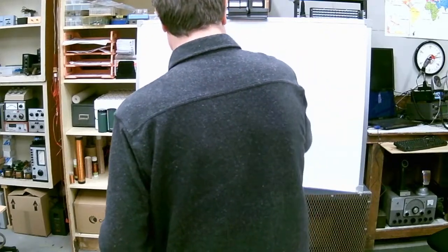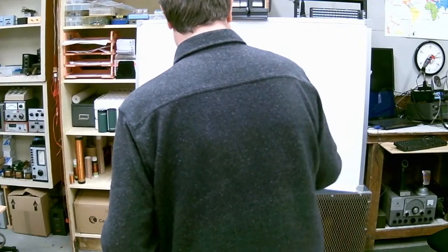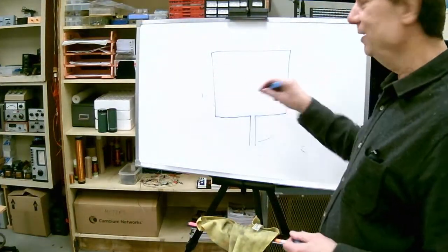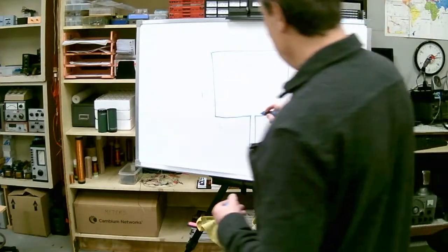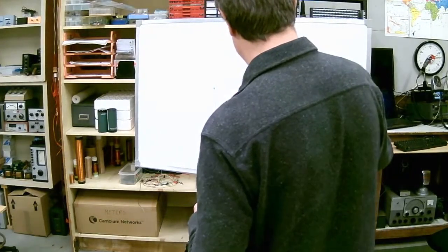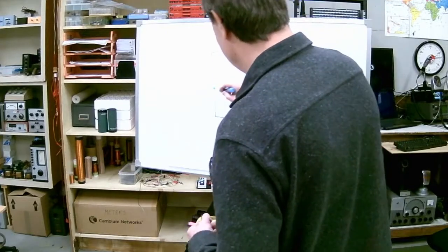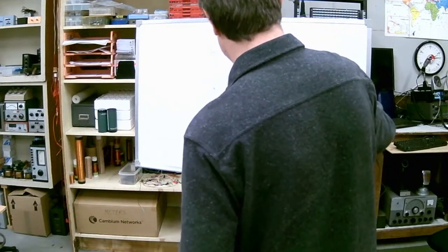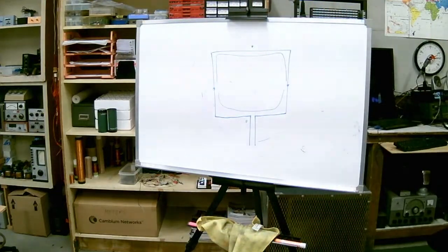And the directional characteristics are unlike the small loop, where it has maximum sensitivity going this way. This is going to have maximum sensitivity broadside to it. And it actually acts almost like you have two dipoles here. This is a full wave on either side, so we've got a quarter wavelength on each leg. Between here and here is about a half wavelength. Here's about halfway. So this comes out being about a quarter wavelength vertical spacing, and that gives you a little more gain than a dipole in free space.